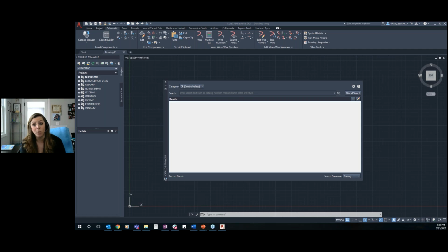When you create that deployment, it is used for every other user, and no one has to do all the manual work of moving around those environment files and repointing their support files out of their AutoCAD options and all the other stuff we have to do when we manually make those adjustments. So I strongly recommend that you do that from the deployment and go through that install wizard. If you want to go deeper into any of that, there are a ton of AU classes on this.